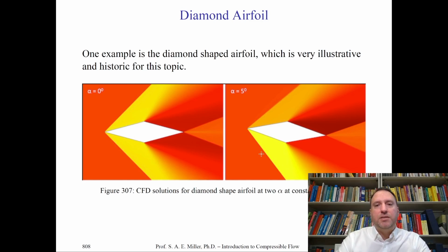the airfoil. So remember, you'll have shocks where the flow turns into itself, and expansions where the flow turns out of itself. The flow moves from left to right, and of course, the streamlines are discontinuous on the shock fronts and continuous everywhere else in the flow.